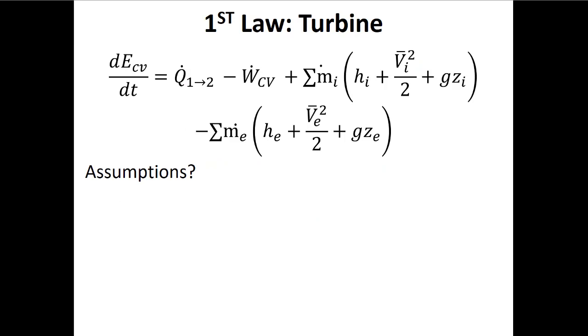So we define these isentropic efficiencies by comparing the ideal process and the real process. But the way that we do that is we talk about the energy benefit of the different process. And for both turbines and pumps, the reason we're running these processes, right? So we run a turbine to extract power from high enthalpy fluid. And we run a pump to add power so that we can increase the enthalpy in the fluid.